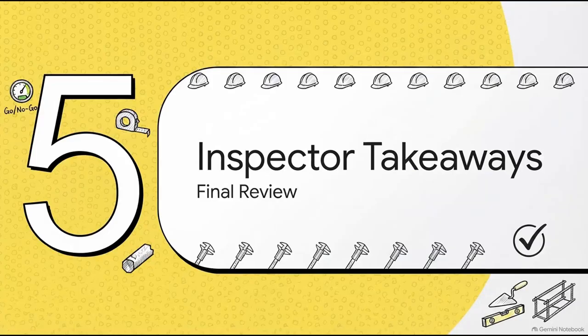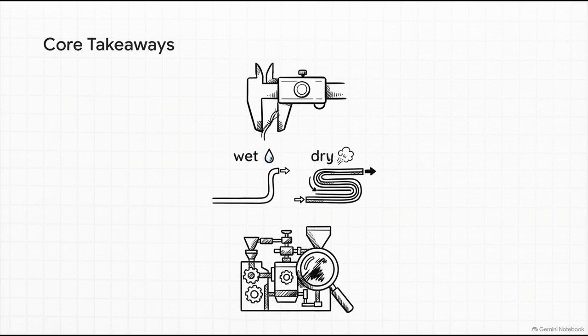Wrapping things up with Section 5, Inspector Takeaways and our final review. Let's distill everything we've talked about today down into 3 core rules you need for the exam and for your daily site checks. Number 1, remember that 0.012-inch threshold. That's the magic dividing line separating structural macrofibers from shrinkage-controlling microfibers.